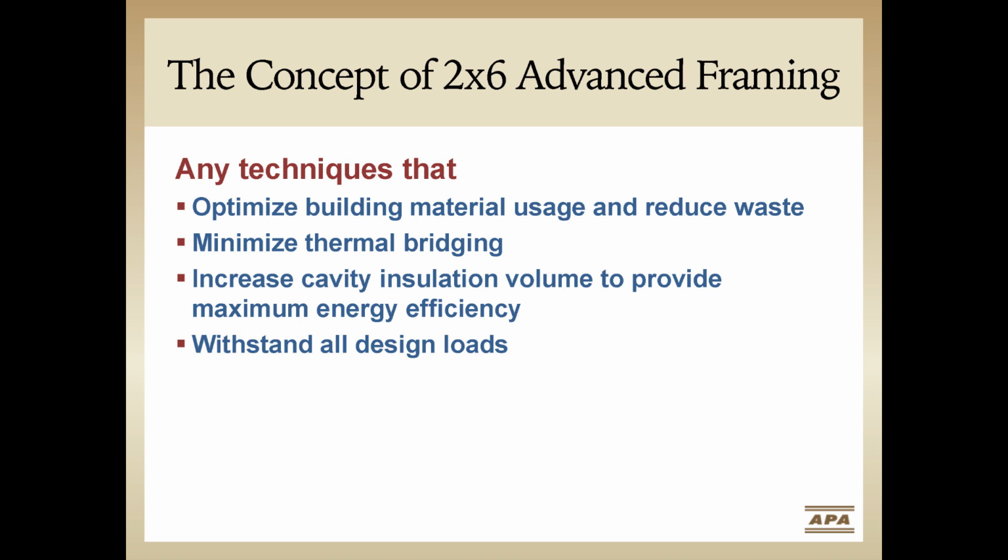The overall objectives of advanced framing can be summarized very simply into these four concepts. When I talk about advanced framing, I'm talking about any details that optimize material usage and energy efficiency, minimize waste and thermal bridging, and resist all design loads. There may be additional strategies that I don't mention today that fit into these objectives. Those strategies would also likely be considered as advanced framing techniques.